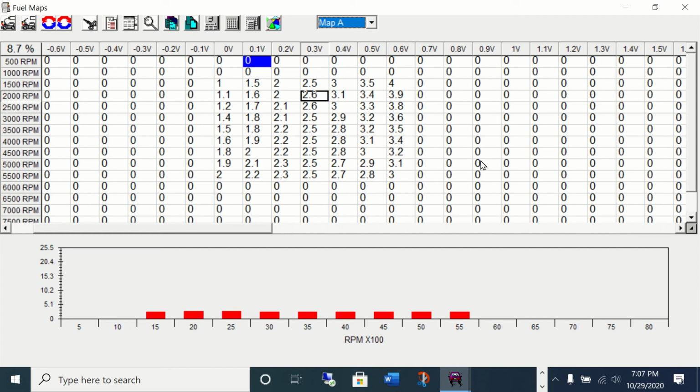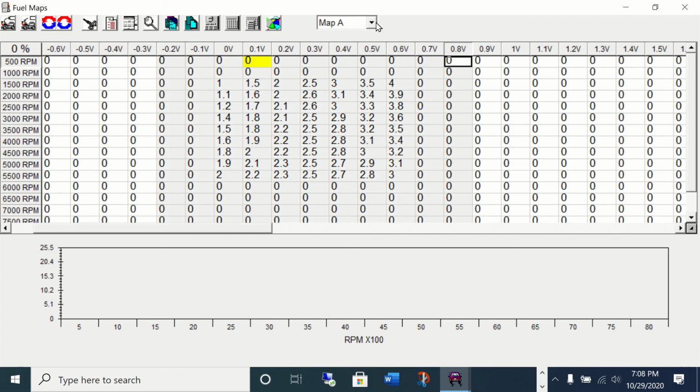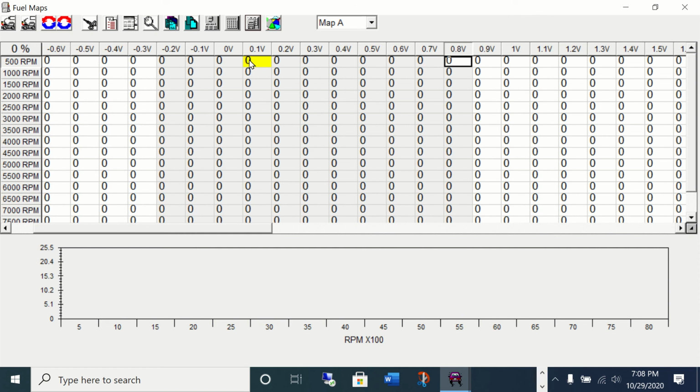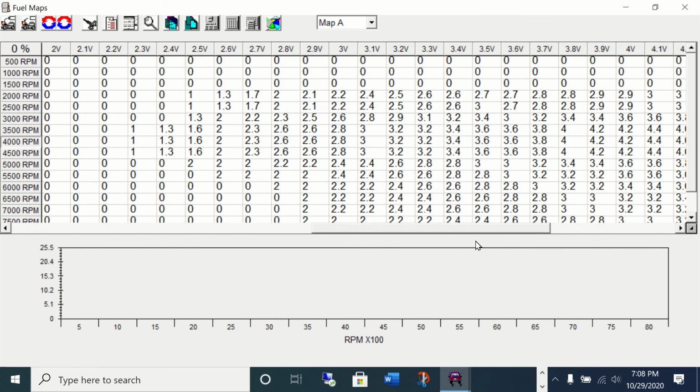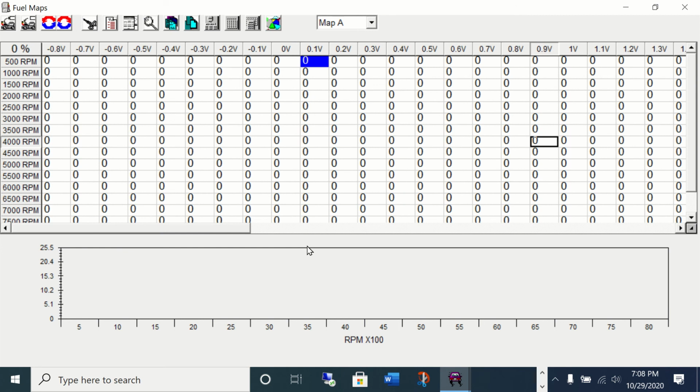But let's say we're using an AIC1 A4H for port injection, and we want all 4 injectors to be driven the same way. Well, we want the same values in both tables. So I can just get rid of these numbers here just to make things nice. And so let's say we've been working in table A and we got all these values, we like them, and we want to put those same values in table B. So all 4 injectors are operating the same way.